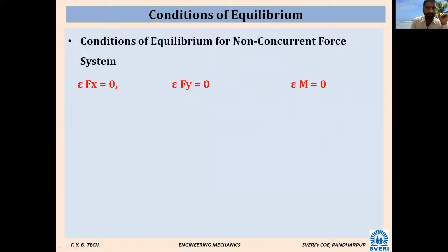See, this is what the question was asked in the ISC and unit test. Correct? Conditions for equilibrium for non-concurrent force system. For a non-concurrent force system, what are the conditions? Sigma Fx is equal to 0, sigma Fy is equal to 0, sigma M is equal to 0.